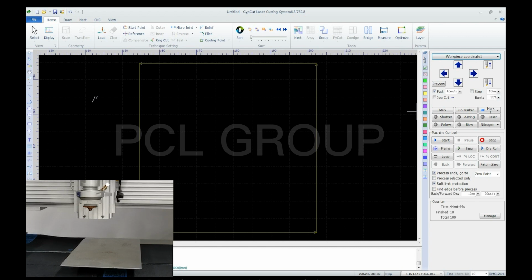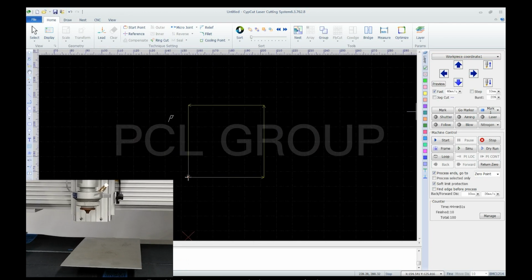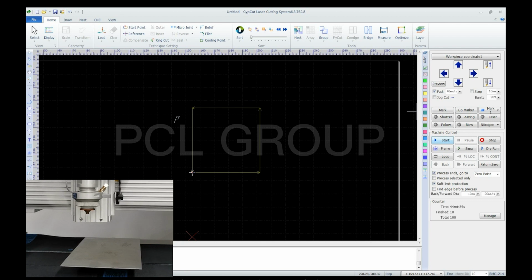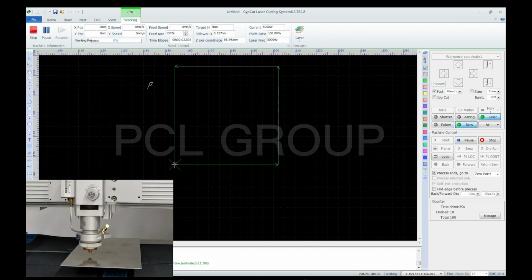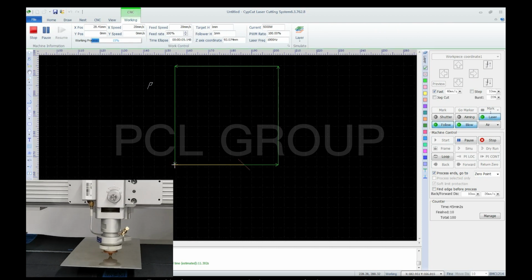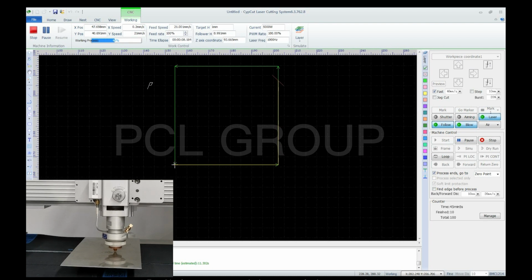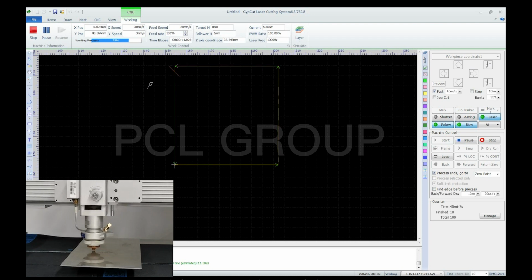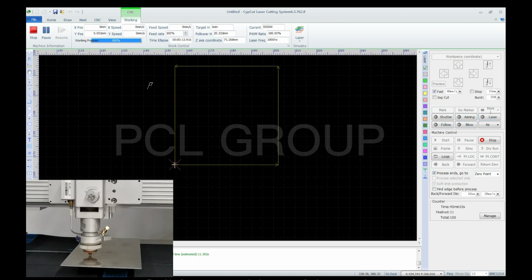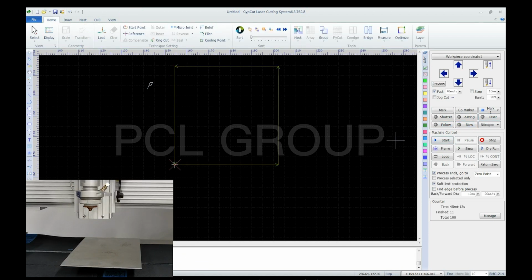During the process, if the cutting head was moved to other position, so long as it gets an instruction to start, it will return to the graphic that is next to the defined 0-point, and then start cutting. This coordinate is used in mass production scenario that a large quantity of plates of same size placed in same position on machine bed, which also requires a 0 point of fixed position.